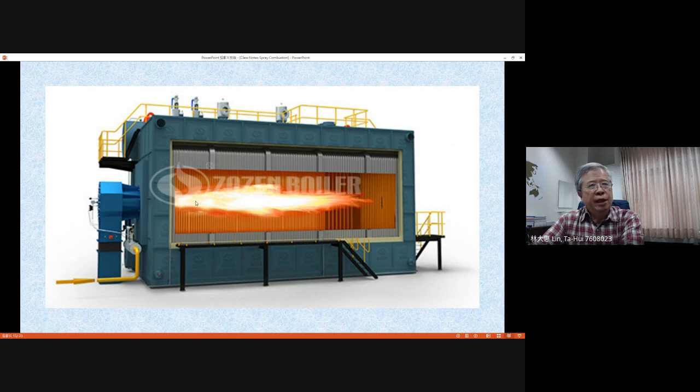Therefore, the flame will extend to a longer distance without any change of the flame shape in this region. The influence of natural combustion is relatively weak for this combustion chamber. But generally, you can see this typical spray diffusion flame, with the spray coming out and burning with the surrounding air. And they show you the diffusion shape, okay, the yellowish spray flames.